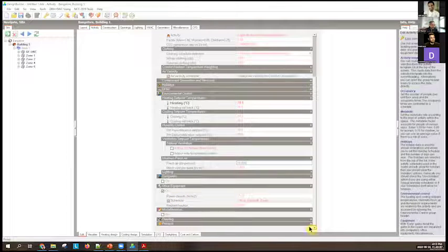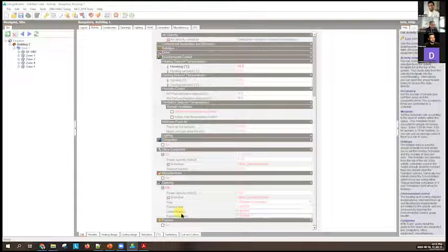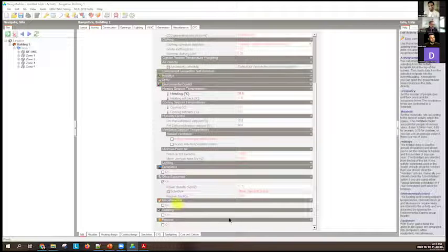And then this one is plug loads. Now there are a few ways of putting in plug loads. There's not any difference between any of them except in the catering load, because in the catering load you can actually specify the latent fraction, how much humidity is coming into the air. Now, unless you've got a kitchen or something, maybe don't worry about it. Give the other loads, because the moisture loads from the air and from the people will get looked after at the system level. Okay, I won't go any deeper right now.